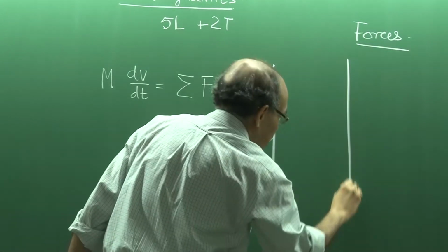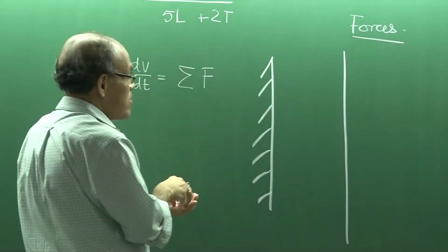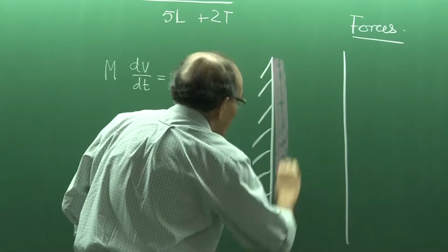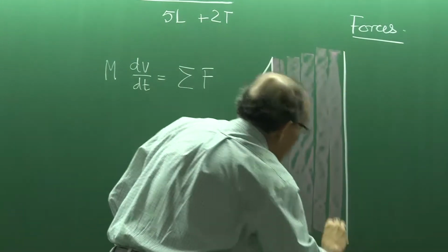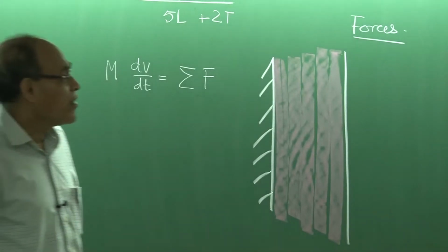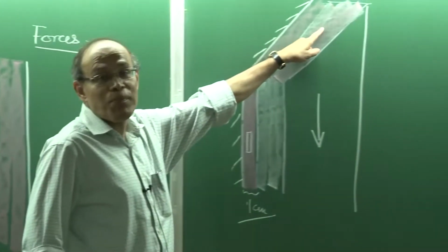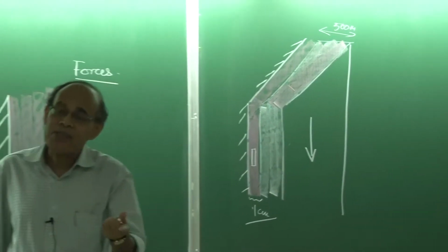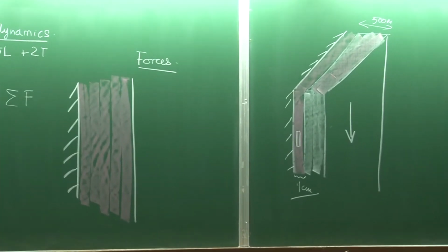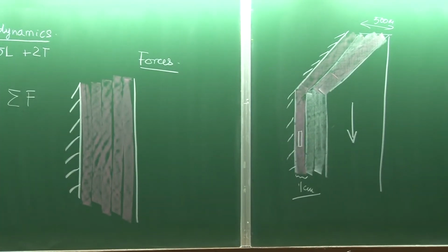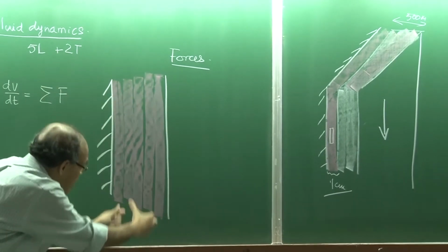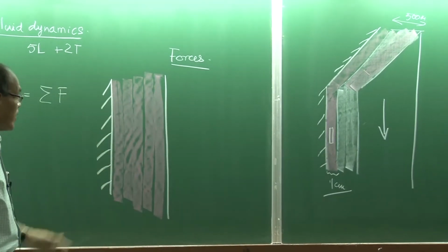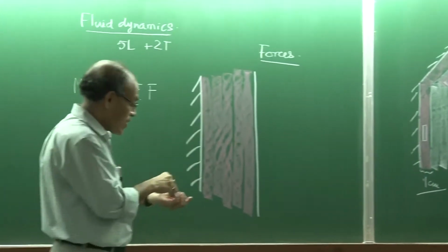This is my solidifying casting, and this is the space that is filled with my molten slag powder or molten lubricant. These are low melting point powders that are sprayed over here, containing calcium oxide, sometimes silica and alumina in various proportions, and they will melt to form the lubricant here. And the entire lubricant is going down, and it goes down because the casting itself